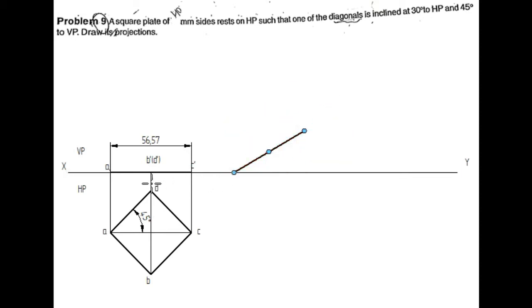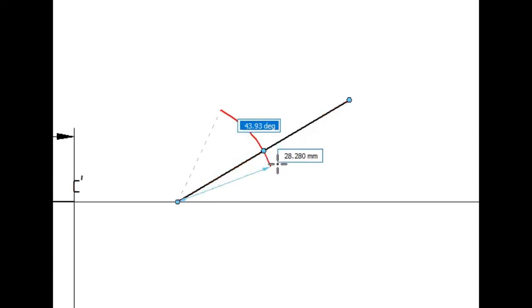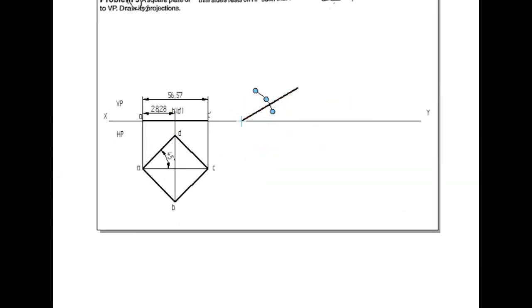Yes. Now the midpoint of this line is at a length of 28.28, right? So I will mark a midpoint of this line. So I will use an arc by center point and cut an arc 28.28 and I will cut an arc. Yes.